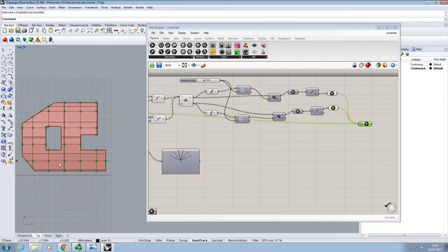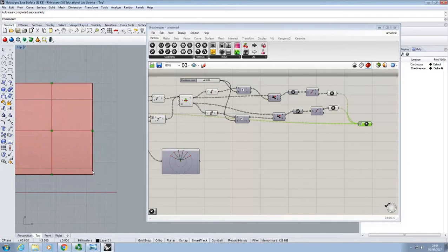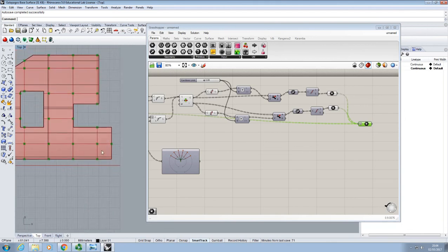So we can imagine that as well as this frame of beams here, we maybe have an edge beam that runs around here to stiffen up that edge. But where we have corners like this, we're probably going to want to put in another column there to pick up that corner and stop that whole thing just sagging down.